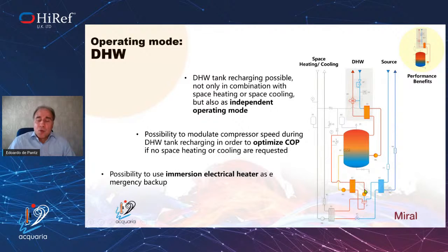Obviously, in this situation where there is no space heating or cooling demand, the system can optimize the COP during the tank replenishment mode, modulating the compressor speed or the pump speed.